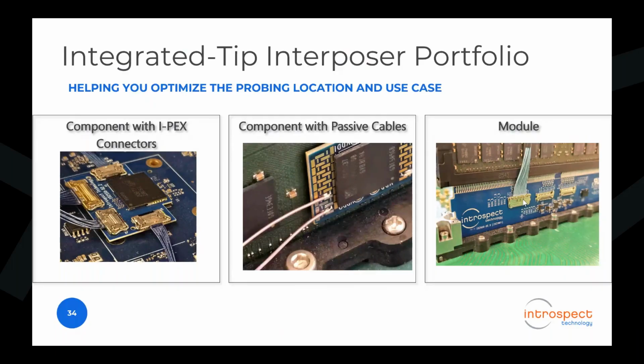Do you support other termination modes for the RSH, like active termination? Yeah, that's a good question. Especially on the riser here, especially for DDR, where the termination is up instead of down. So the circuit, and you can see some regulator circuits here. There are some circuits here to create a termination level so that the tip is terminating to like 1.1 volt